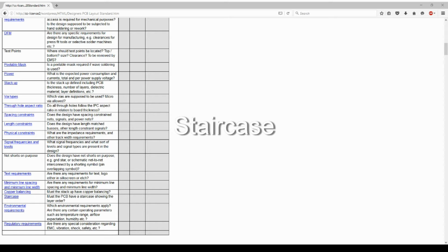By making a staircase with numbers as copper edge on each layer, and having an opening of the solder mask and pulling back other copper area, you can see through the board and see the numbers written on each copper layer, so that you can verify that the production, the assembly of each layer is correct, so the order of the layers are made correctly.